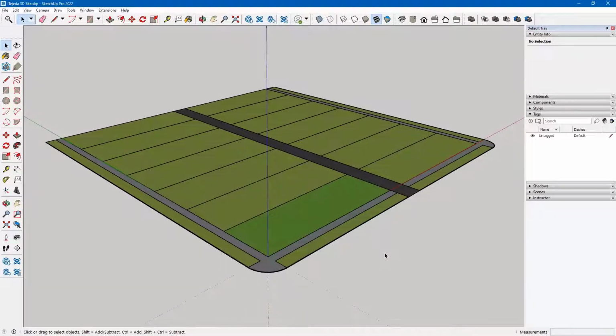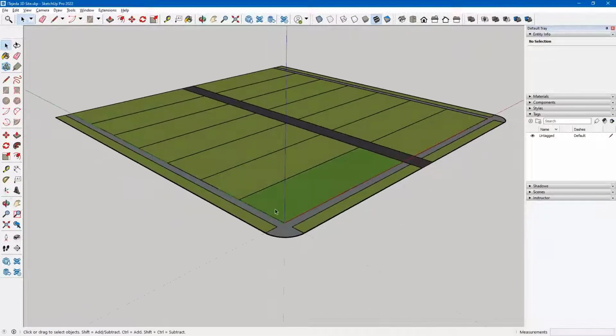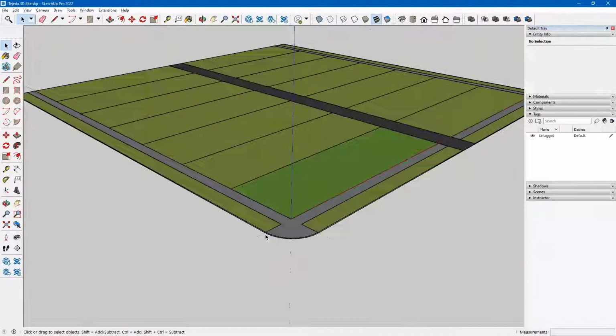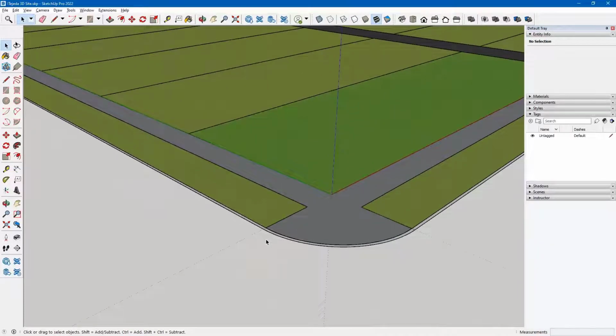I just need to put it into the areas where I believe I'm going to see it in my model when I generate my views. Only in the areas that pertain to what I'm doing, I'll focus on that. So for the street, I will go ahead and begin right here at this location by the corner. And I'd like to extend the street out, I'd say at least 20 feet. I don't want to model anything on the other side of the street because it's not really necessary at this point.